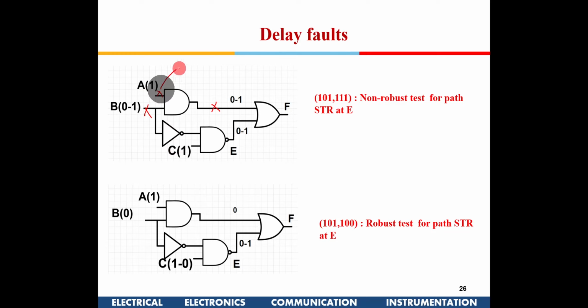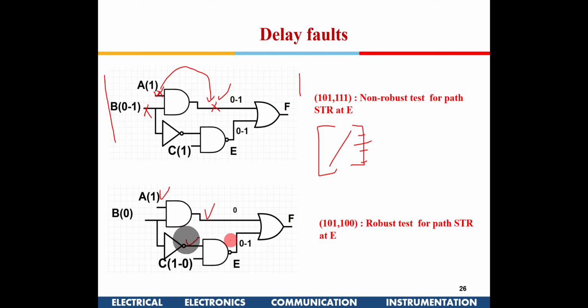Now, is it possible that this fault and this fault are the same, as far as the test vectors and the output are concerned? If I test this, automatically this also will get tested. Then my total fault set will reduce. If I am trying to find equivalence faults, if this fault is equivalent to this fault, then this list gets compressed, and if this list is compressed, then my algorithm will run faster. I will not keep duplicating the test, trying to find this fault and trying to find this fault. So I have to first collapse the list.